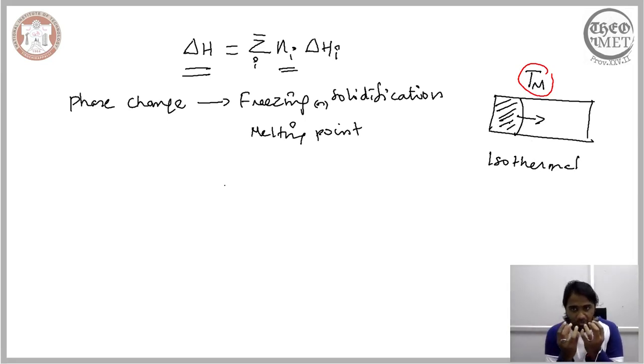So in order to ensure that the solid part of the system is below the melting point at temperature Tm, we need to remove the heat out of the solid part, and the heat is sent back to the liquid part. The heat that is sent to the liquid part ensures that the solid that is formed is at the temperature Tm and it is in the stable condition. So what we are doing is removing heat from the system. Initially this heat is being transferred to the liquid, and finally the heat will be transferred out of the system to the surroundings as the solidification reaches the end.